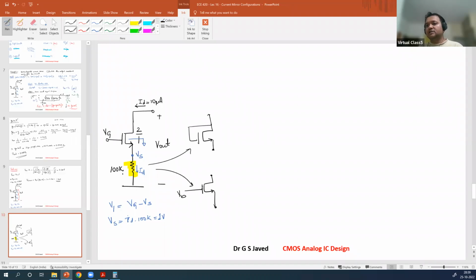So if you replace this 1 over 10 with this one, what do you get? This 100 should provide the same value. So let us suppose you use this circuit. The output impedance of the diode circuit is 1 over GM. In that case, 1 over GM should provide a 100 kilo ohm resistance. That would be the R out 1 of this device.